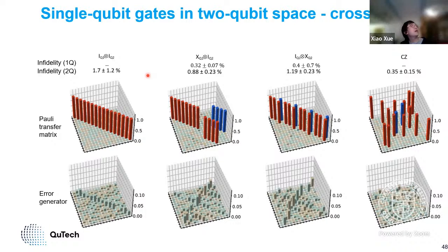For long range crosstalk, this is also a very good point. In silicon or in semiconductors, we normally assume that the errors come from charge fluctuators, which we refer to as charge noise, and from some residual nuclear spin or residual hyperfine interaction, which should also be local. Okay, a charge fluctuator is not really local. It still has an impact across a certain range, so that cannot be considered really local. On the other hand, when you apply a microwave signal to a metal gate, the metal gate has a huge capacitance to a lot of qubits. So that can give you some non-local electric noise. So I agree that there will be local noise and non-local noise.